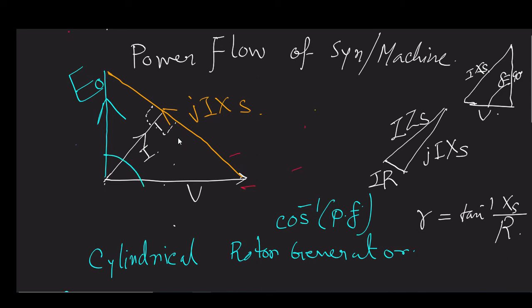And this gives you delta is equal to 90 degree. This is a physical case, while having finite V and E naught is allowing you, rather if you see that the magnitude of E naught is smaller than V, because this is a capacitive case, leading current. The machine is connected with a capacitive load that is drawing leading current, and therefore you are having negative regulation. All these are good, all these are good, but now